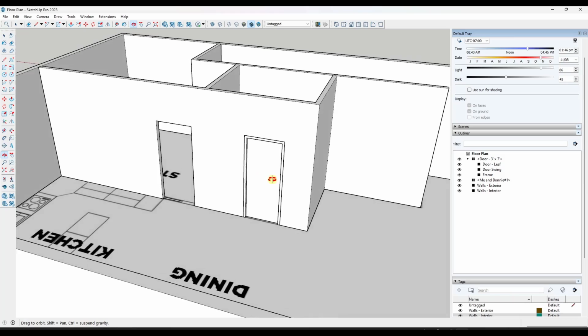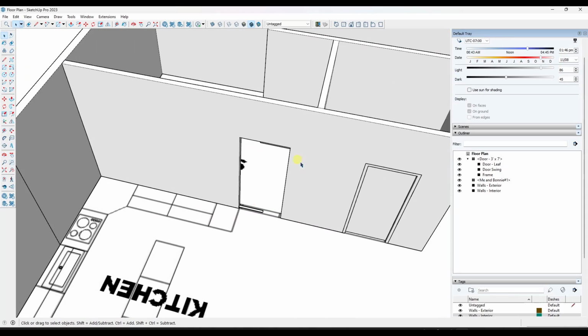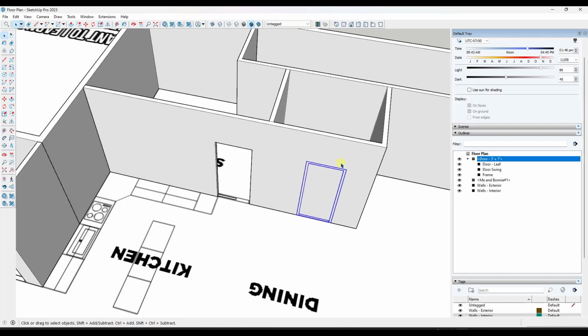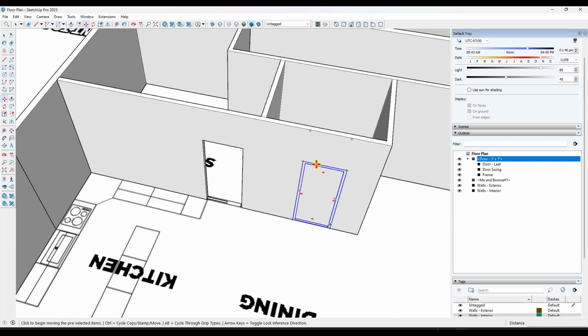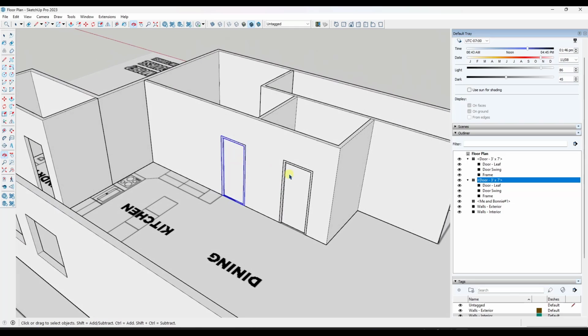And in a lot of cases, we can reuse these doors. Technically these are in here as pocket doors, but for this one, let's go ahead and reuse it. So I'm going to use the move tool in copy mode and copy this across right here. So just M key, click, and then tap Control on your keyboard in order to go into copy mode. But now I've got 2 doors in here.